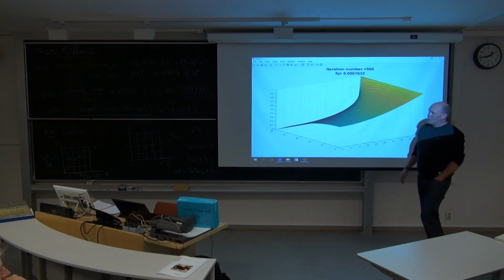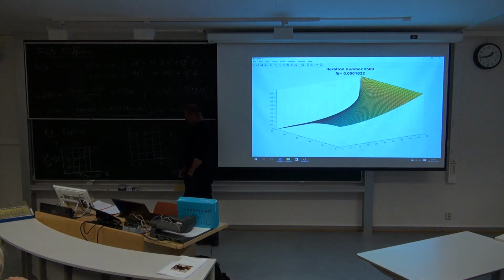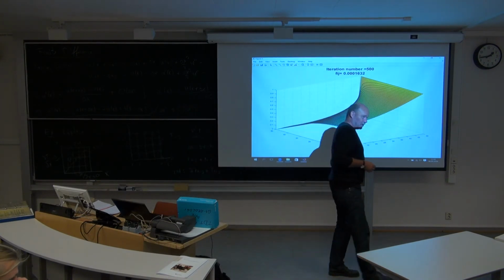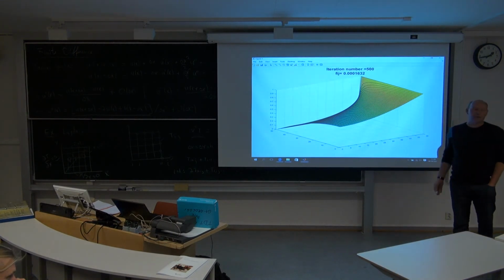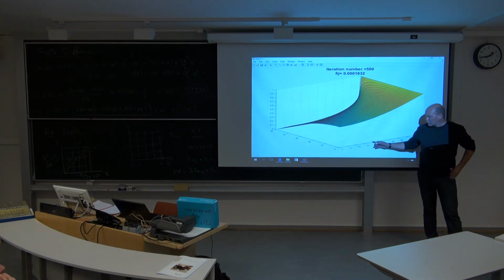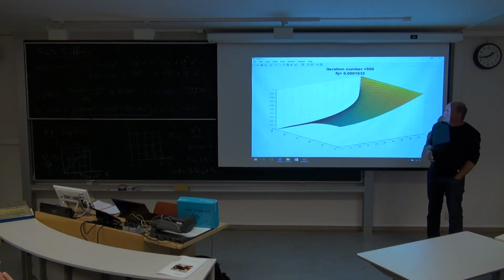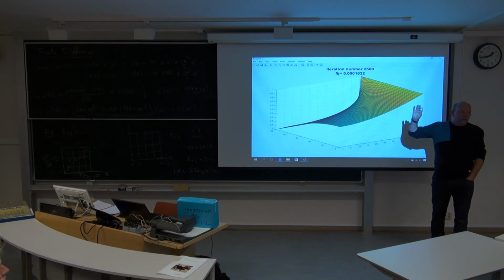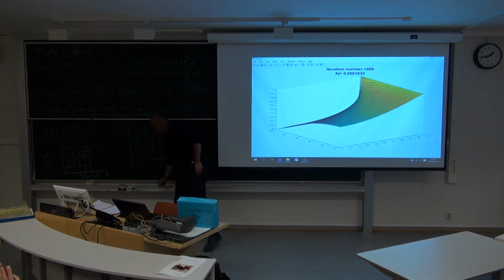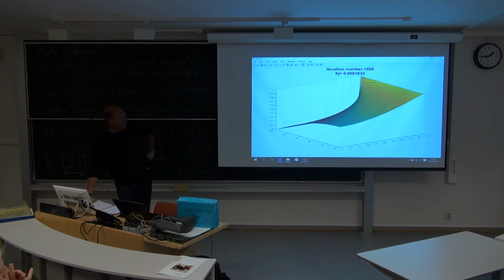Furthermore, remember the problem at hand. We are actually trying to solve this equation here, double derivative equal to 0. We have used finite differences, so we have a discrete representation of the real partial differential equation with some errors in it already. And the error is of second order, so meaning it's a delta x square. That's the type of the error. So yes, you can solve this equation system all the way down to machine accuracy if you like, but why waste time? It's a lot of errors there already. So you should definitely stop before you just burn up your CPU unnecessarily.